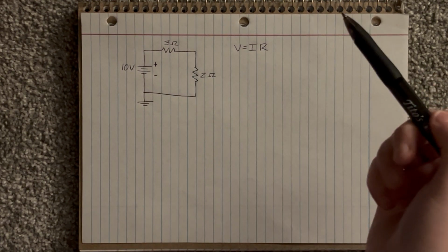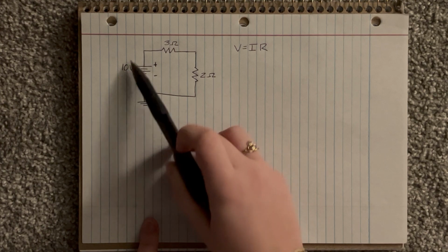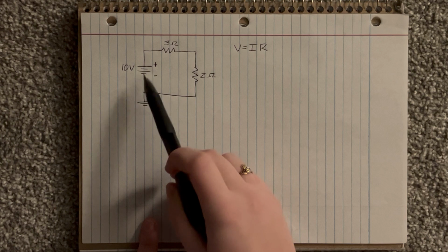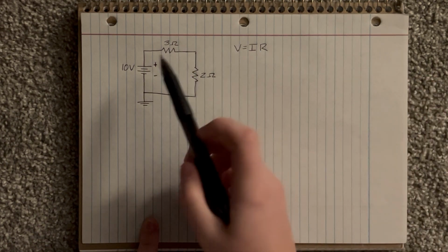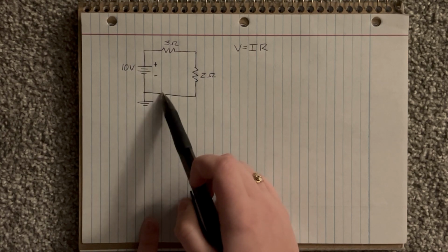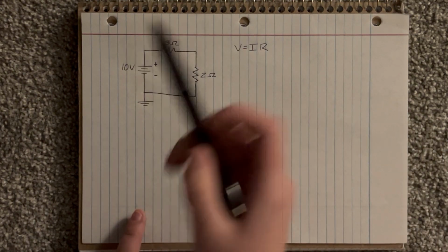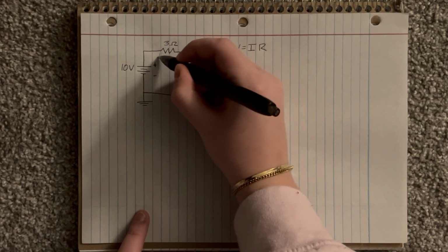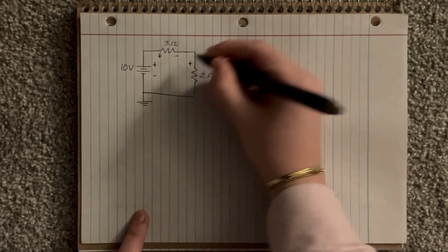Now, current in a circuit goes from high to low, so the voltage here will be 10, indicated by the voltage source, whereas this is ground, this indicates that there is 0 volts in this section of the circuit. So the current is going to go from the high voltage here of 10 volts down to the low voltage of 0 volts. So that means that the potentials across the resistors will go from high to low. And the same here, high to low.